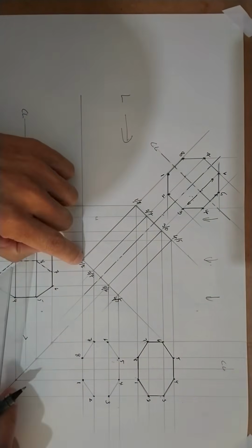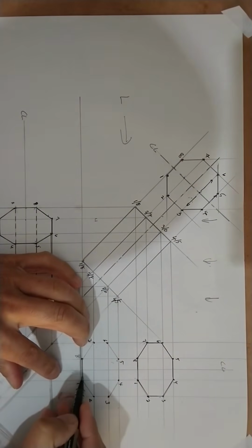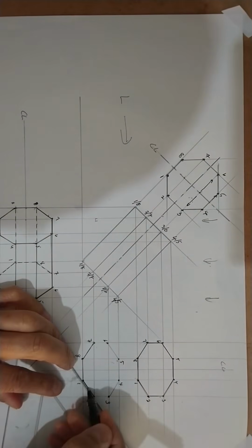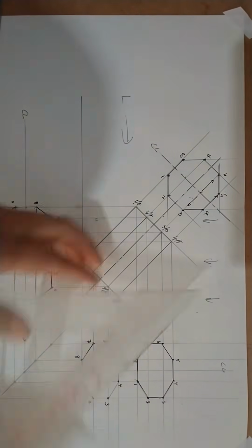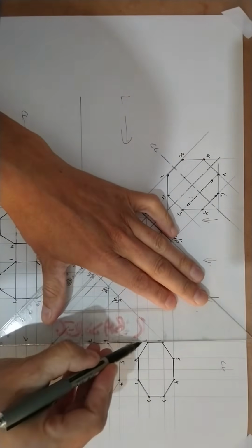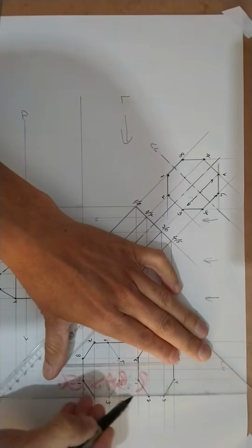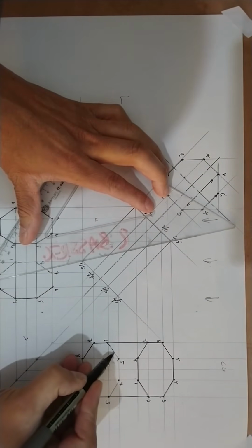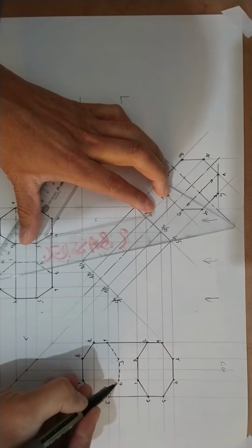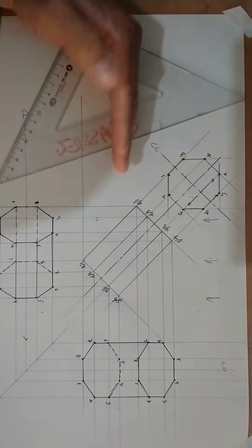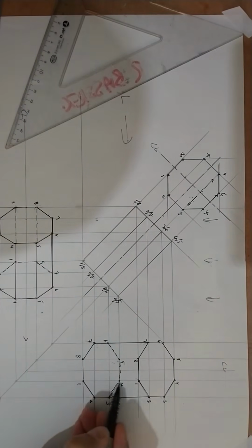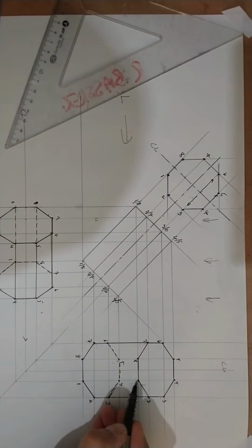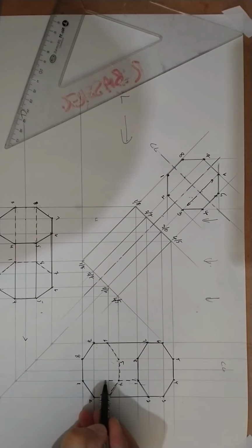And then I'm going to see the bottom one here. I'm going to see this to the side. But I'm not going to see that going in. But number 7 must connect with my number 7. That's my side. Number 2 must connect with number 2. These are going to be dash lines again. Dash lines, because I won't be able to see them from this side, and those are the corners that I won't be able to see on that side, which is number 1 running to number 1. So from there it's going to be dashed.